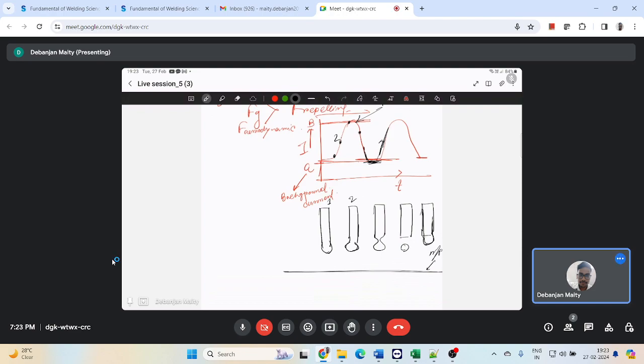These kinds of welding techniques mostly use filler wires, and that is melted by the application of heat without forming a part of the electric circuit. So this is completely an external source of deposition, what you are trying to fill into the gap, right? So no electromagnetic force will be responsible for this metal deposition.